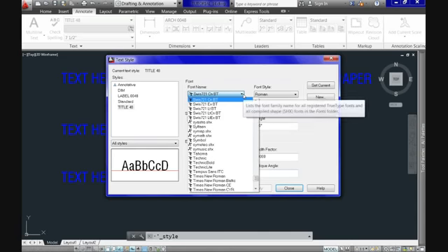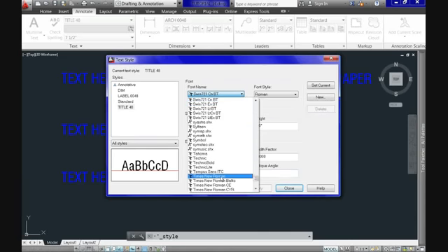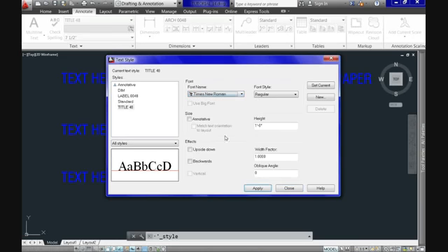As you see in the font area, using the drop-down menu, you can select the font you prefer. In my case, I'll use Times New Roman. As you see down here, we have a preview of the style, so use it to see if you like it or not. Now to the right, we have the font style. Pull the menu to see that this refers to bold, italic, etc. And try it to see the results on the preview. As you notice here, this checkbox also indicates that we can make our style annotative, and for now we won't use it.